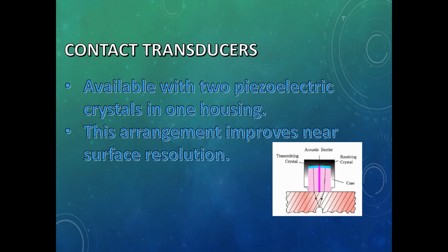Contact transducers are available with two piezoelectric crystals in one housing. These transducers are called dual-element transducers. One crystal acts as a transmitter and the other as a receiver. This arrangement improves near-surface resolution because the second crystal does not need to complete a transmit function before listening for echoes. Dual elements are commonly employed in thickness gauging of thin materials.